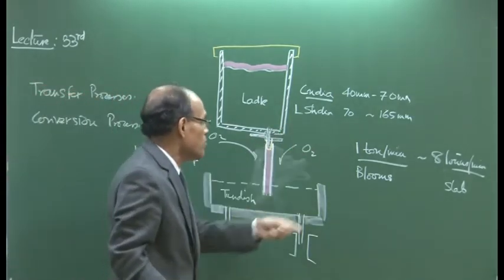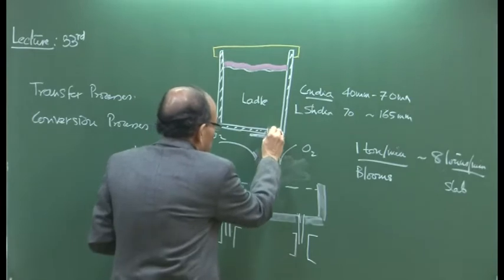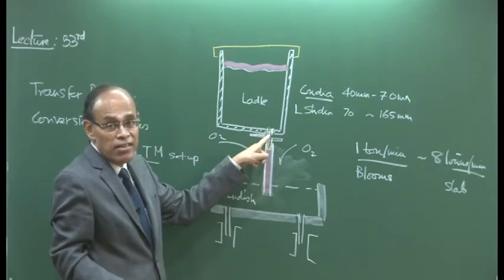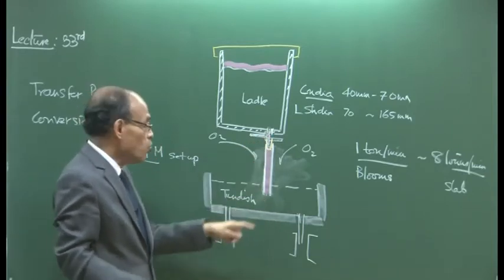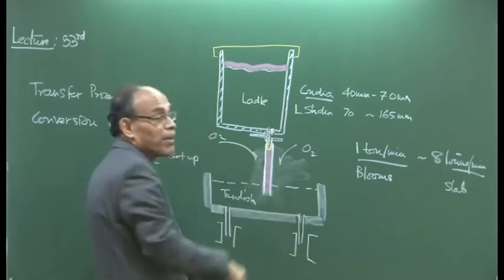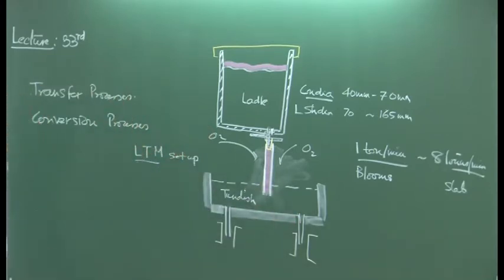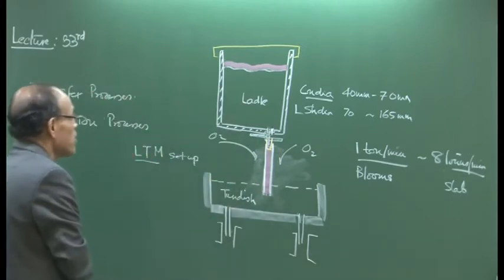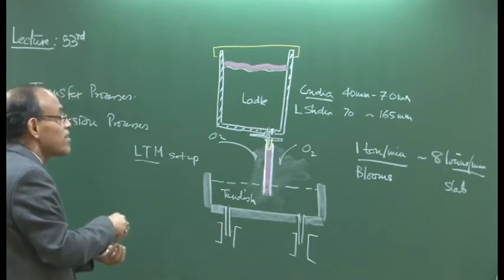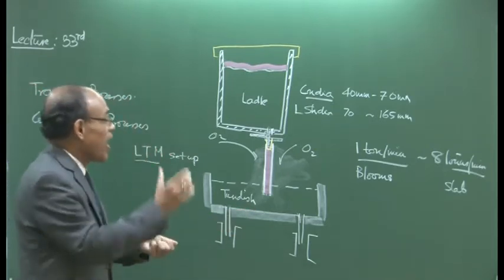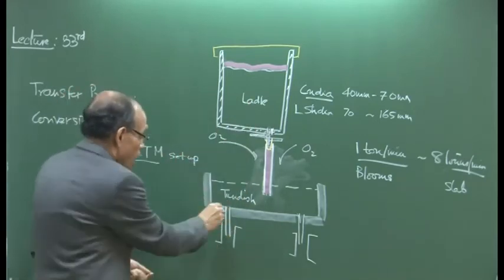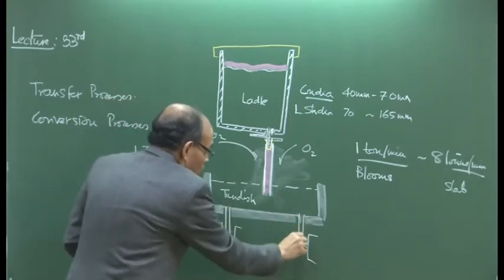So, that is the rate at which molten metal flows. We cannot afford to drain molten metal at too large a speed, because first it is going to erode the nozzles here, and secondly it is going to induce a huge amount of turbulence in the jet impact region here. So, there is a limit to which we can transfer molten metal from the ladle. The slide gate will allow us to control the flow rate because the head is going down as a function of time. So, the slide gate aperture can be controlled, and as a result flow can be very high or very low, or the flow from the ladle and tundish can be matched. The outflow from here through the strands, these are called the strands.